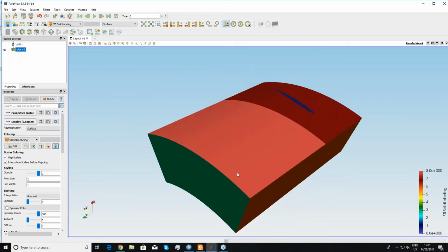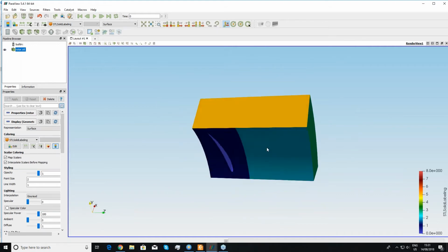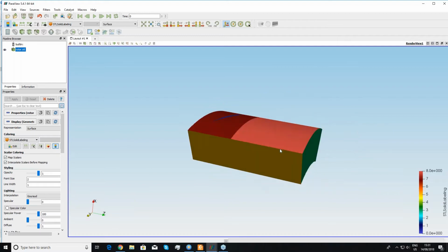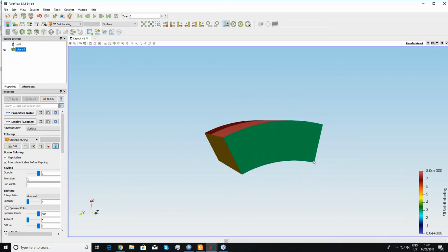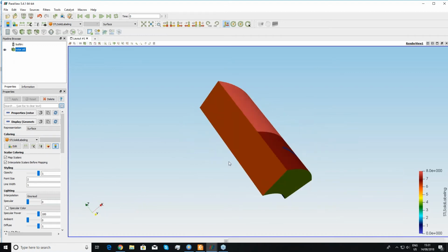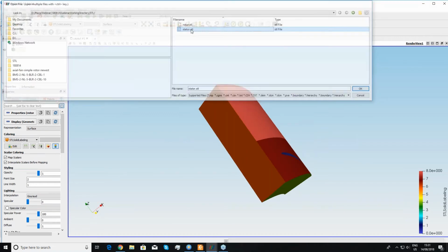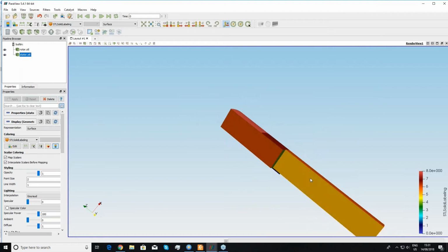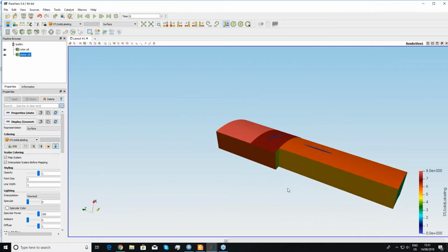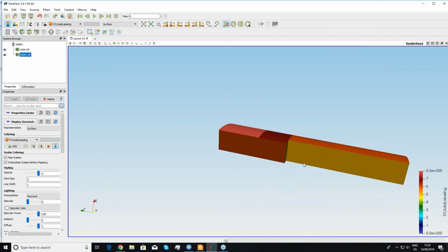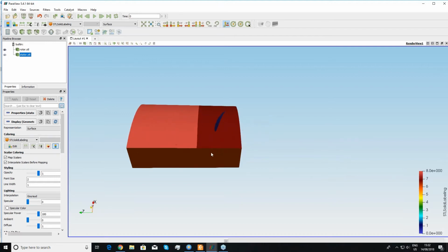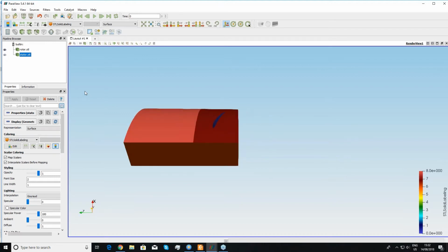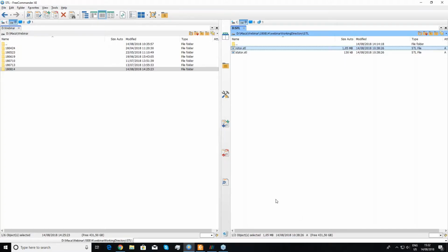So this is the rotor part, split into several parts: two hubs, two shrouds, one periodic boundary, which will then be connected, and the inlet and the outlet. Of course, the full geometry also contains the stator part, but just to speed up the simulation, because I would like to really show you the results live, I will simulate only the rotor part today. So I will take this rotor STL and set up the whole case. So let's go for it.